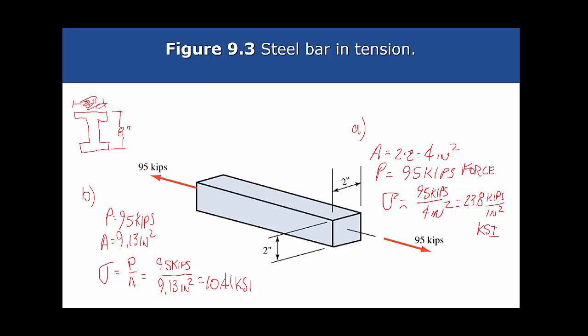of that bed. The 4 legs of that bed have a lot better chance of piercing that floor than that waterbed does. You're going to have more pounds per square inch on that small area, and there's a case involved right there: 23.8 kips per square inch on that 2x2 as opposed to 10.4. So the more you spread that out, the better off you're going to be. So you're looking for more contact area.